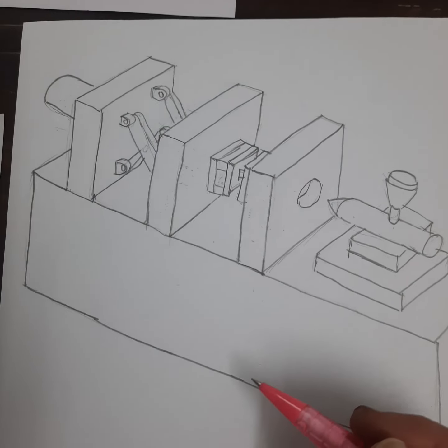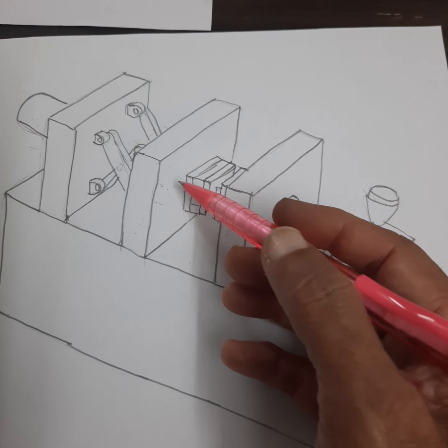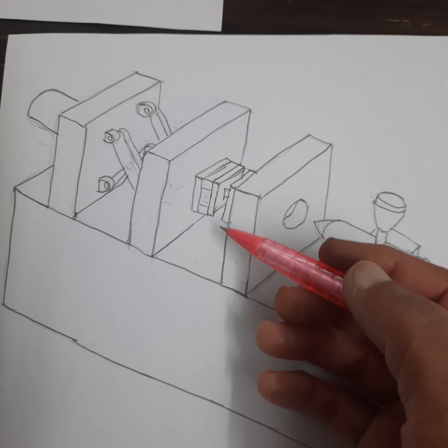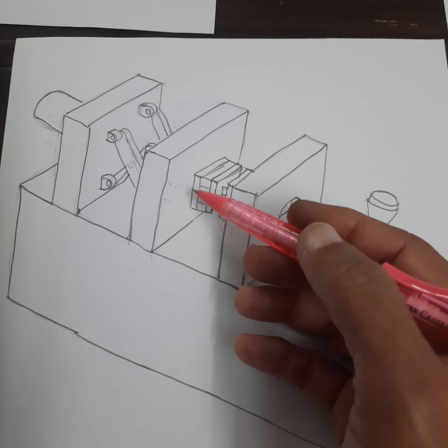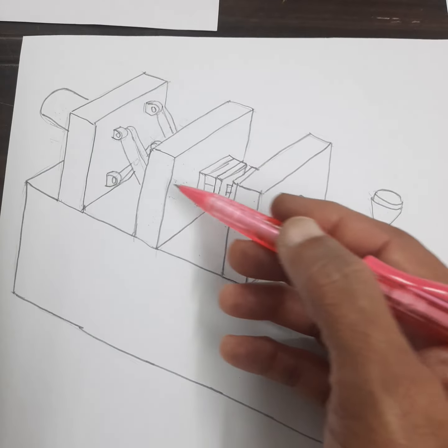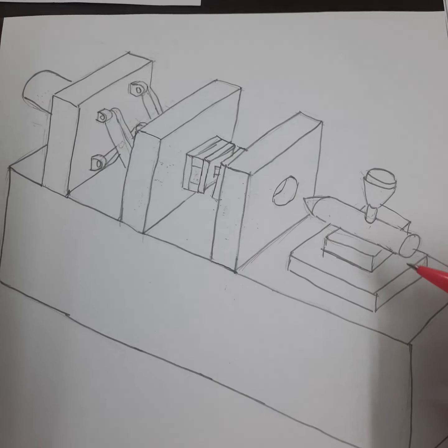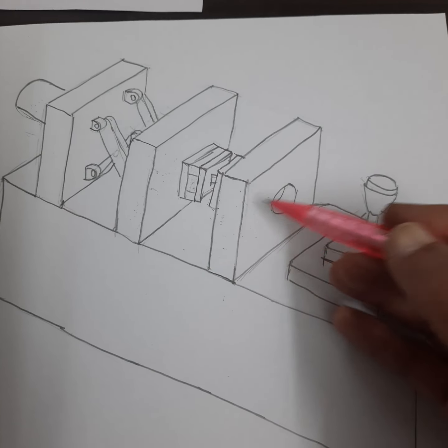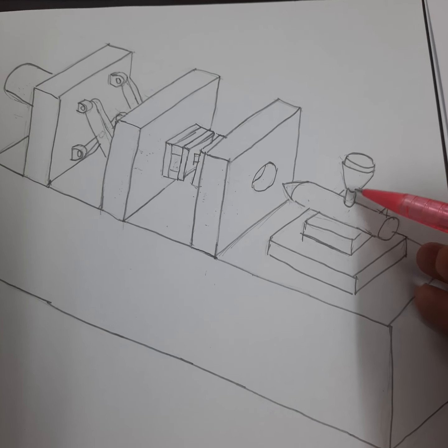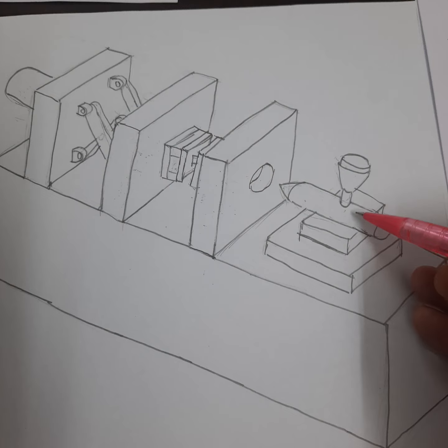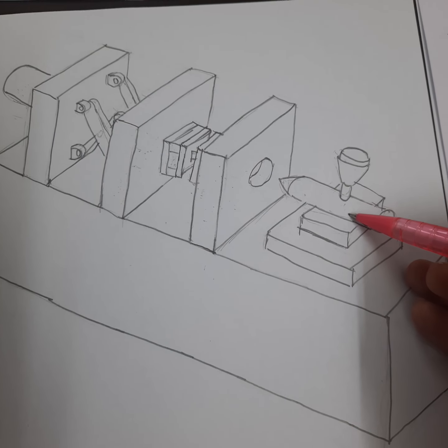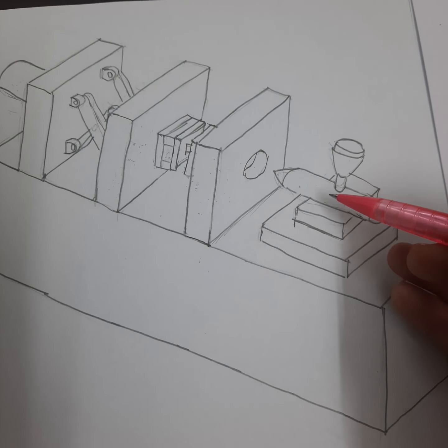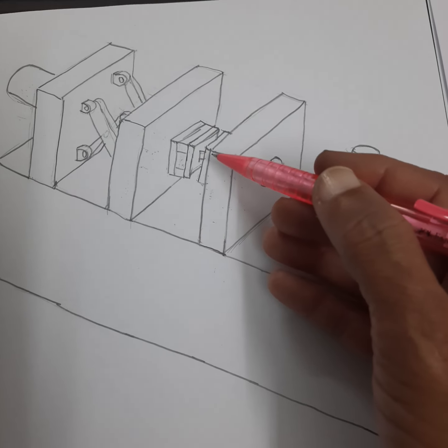The designed molding tool has to be fitted onto the moving and fixed platen. After fitting the molding tool between the moving and fixed platen, we have to move the injection unit close to the fixed platen. The raw material which is fed into the hopper will be melted in the barrel, and the granules become liquid. The liquid polymer has to be injected during the molding cycle.